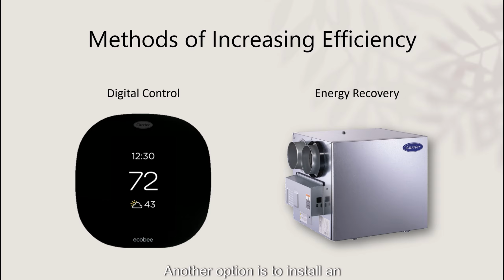Another option is to install an energy recovery machine or some type of energy recovery device. In this case, we have what's called an ERV, energy recovery ventilator, and what it's going to do is it's going to take in outside air and bring fresh air into the space. Commercial spaces do require a certain amount of fresh air, just for sanitary reasons, right? And we have a bunch of people that are inside of a space. If we can't circulate that air, well, people are going to start to get sick. So we have the ERV that helps bring that fresh air in.